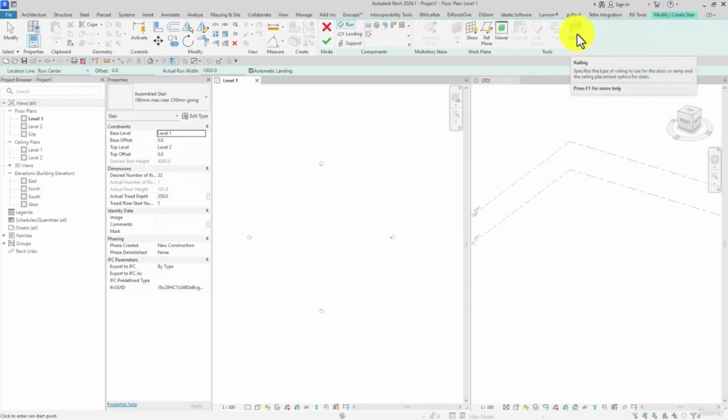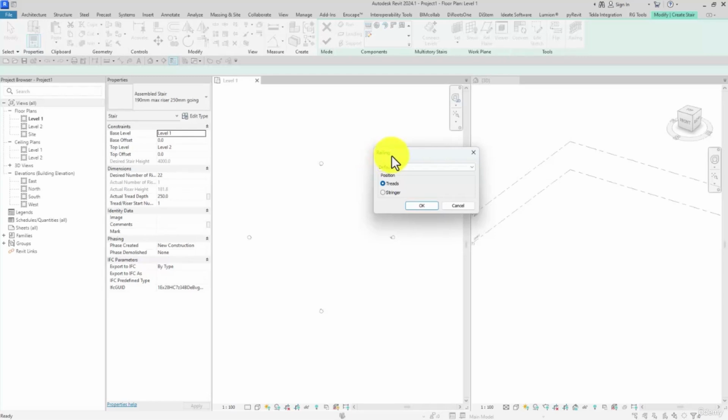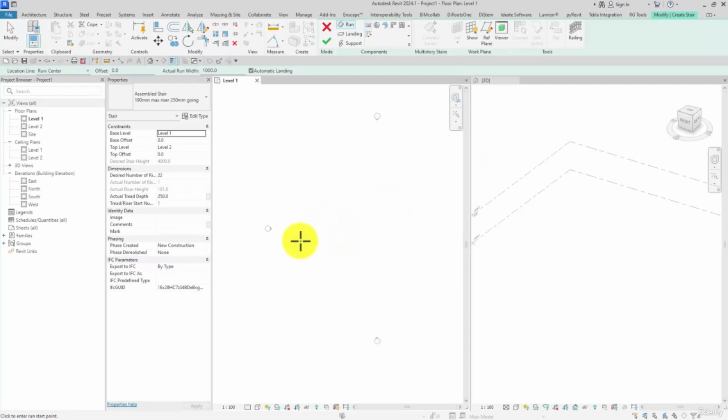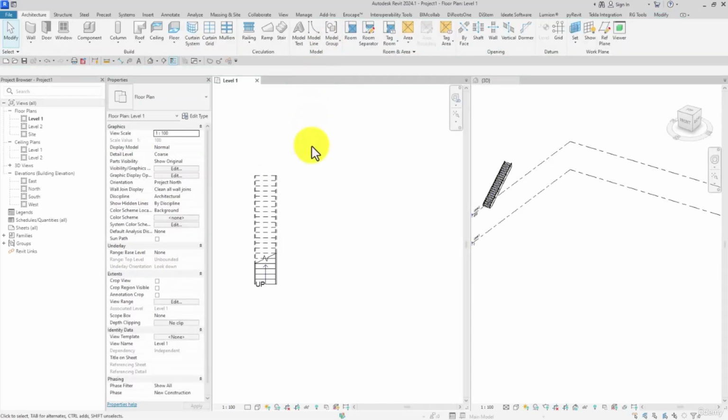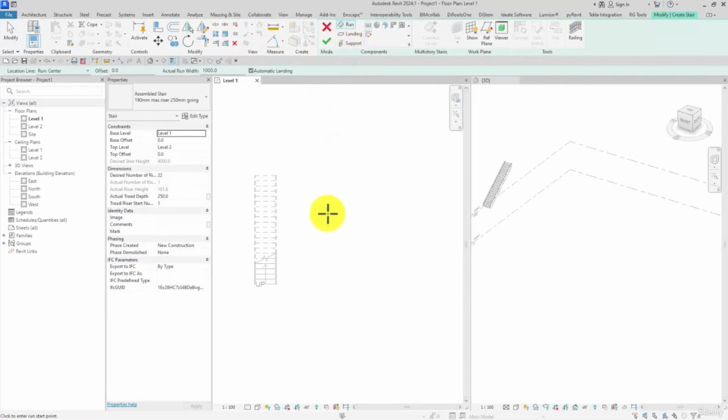But here from railings, I click on railings, and then I set the railing to none, since I don't want the railing to be added on the stairs and I want to focus specifically on the stairs, not on the railings. This is the straight run or the straight stair. Note that after modeling the stairs, you have to click on finish, and the stairs are going to be drawn separately. Again, if I select this, we can draw L-shaped